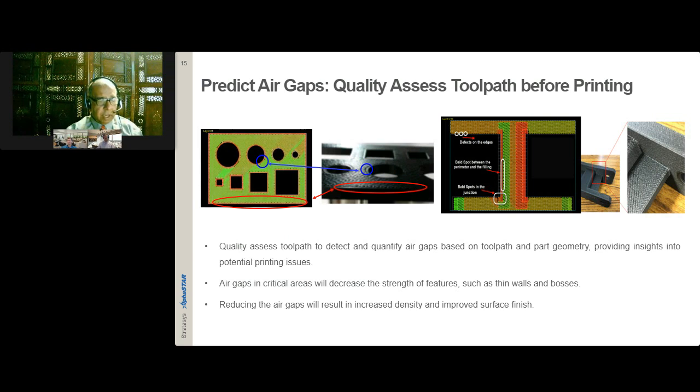As you can see here, as the material, in this case deposition, is laid down on the edges, the movement of the tool path can lead to little gaps, and certainly that could impact the aesthetics, the final quality, the final net shape of the part. But depending on where it is or how the part is ultimately used, it can definitely impact performance, particularly for some of those areas that are noted on the interior of the part itself.